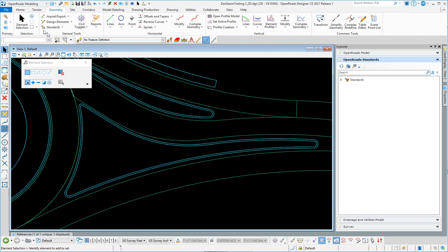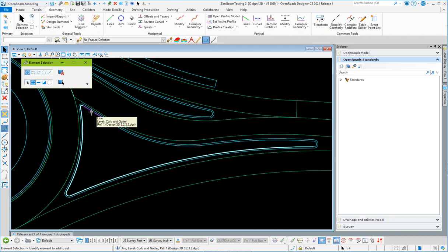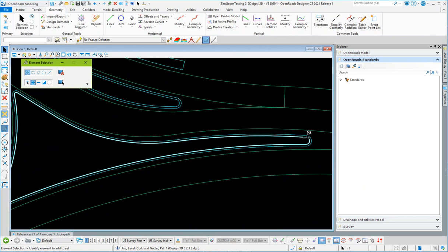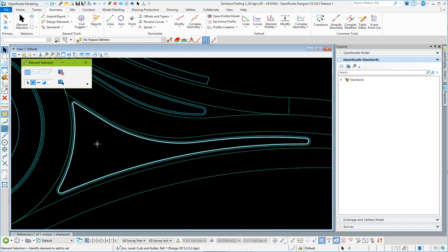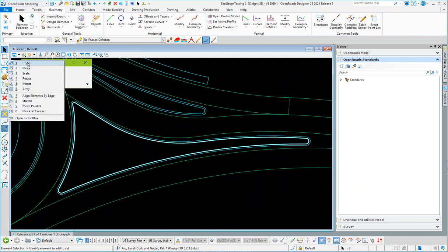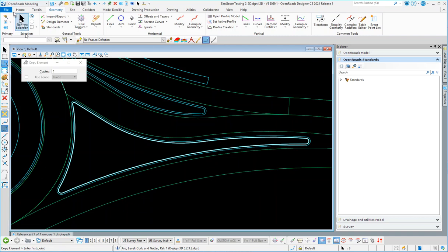I just have this referenced. I'm going to go, as one method, ahead and select this geometry here, or these graphics. Okay, so I have that selected. I'm going to copy it into my active drawing because my active drawing is empty. So I'm just going to go to copy, and in MicroStation, I'm just going to copy graphics in here, and then grab this and do DL equals 0.